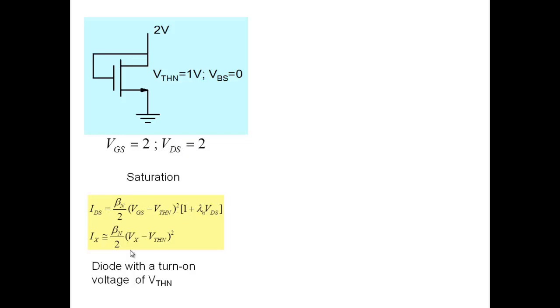The other thing bad about this diode is, normally when we turn the diode on, once we cross VTHN, we want the current to increase rapidly. It doesn't increase very rapidly here. A PN junction diode gives us an exponential rise. Remember we kept saying that once you go above a turn-on voltage and increase the current, the voltage across the diode is approximately 0.7 or whatever. Why?